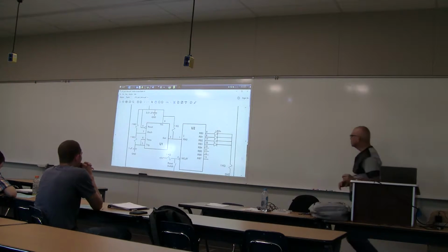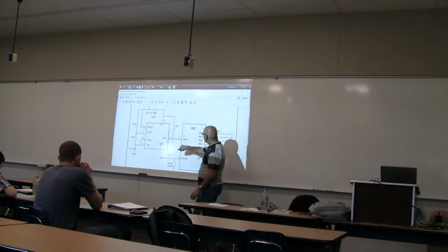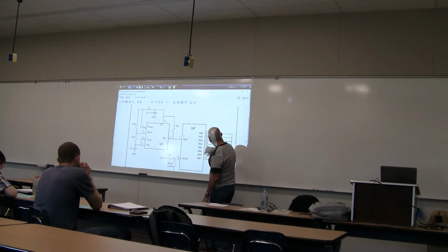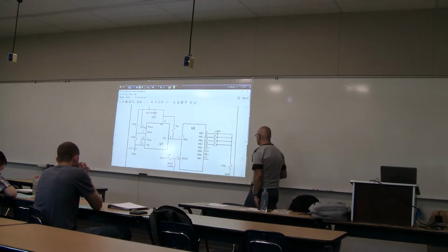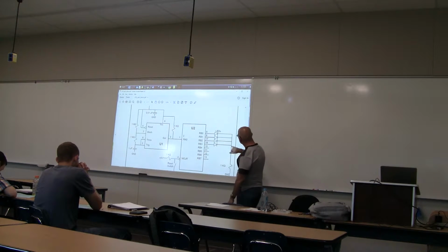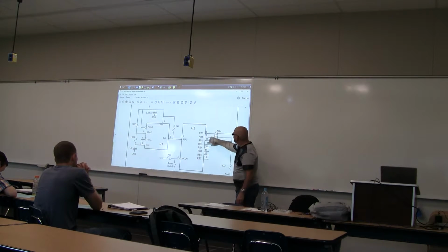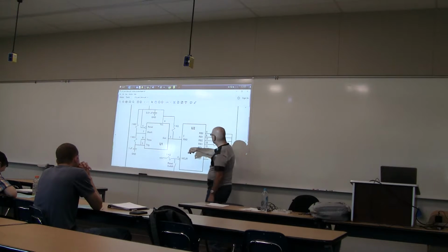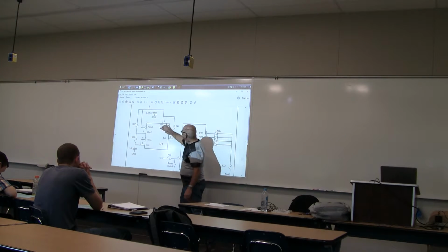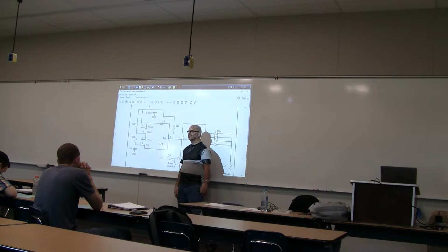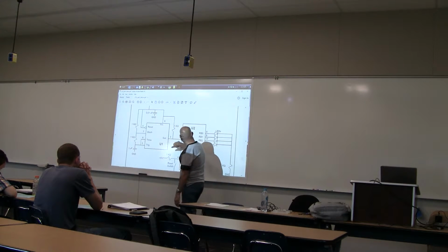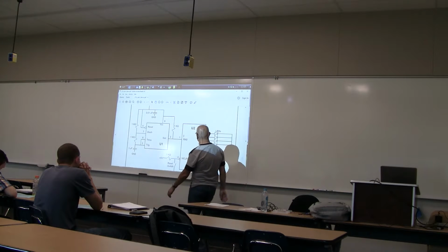So here's our chip. RA0 is our input, and our output is RB0 through RB7. And we're just going to hook 4 LEDs up to these outputs. And to cause the input to toggle, we're going to wire our favorite 555 timer to generate a pulse every 2 seconds. And we're just going to feed that into pin 1, which is RA0.